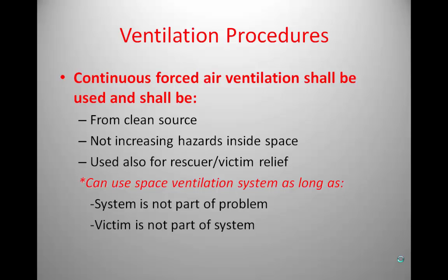We had an issue one day at our trench training where the portable generator was used to supply the power to our duct fan, and wind direction changed, and actually we noticed a spike of our CO with our air monitoring. So that's why our air monitoring is important as well. You can also use your ventilation for rescue or victim relief. Even if the air readings are good, you can still put ventilation in for that relief there.